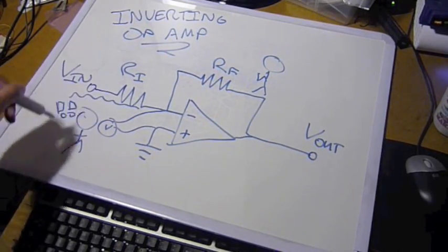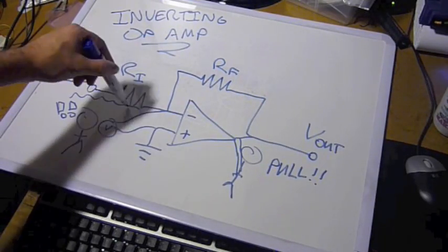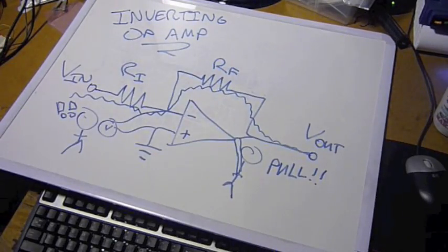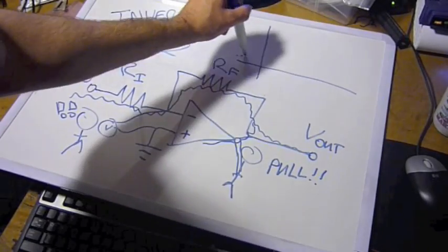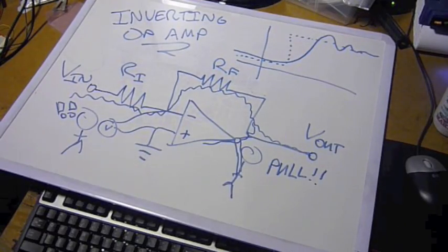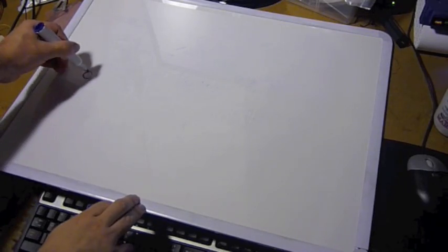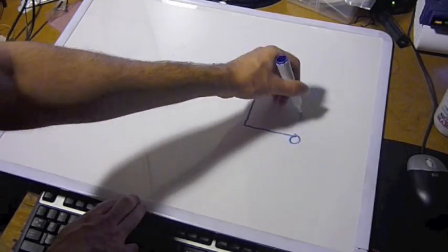As I apply voltage to the input of the circuit, the potential travels across the input resistor here. The op amp notices a difference between the terminals. One's at a positive and the other is at ground. Now, the only way the op amp can rectify this is by lowering the output potential here to draw current through the feedback resistor. Because the op amp has infinite gain, it may sink a huge lug of current in an attempt to lower the output voltage quickly. It might overshoot by a little bit, but because it's constantly monitoring the voltages at both input terminals, it can compensate for this. You'll notice I just explained to you the two magic rules of op amps, except there was no reason behind it. It's a bit of a dangerous analogy though, because there's probably quite a bit wrong with it.